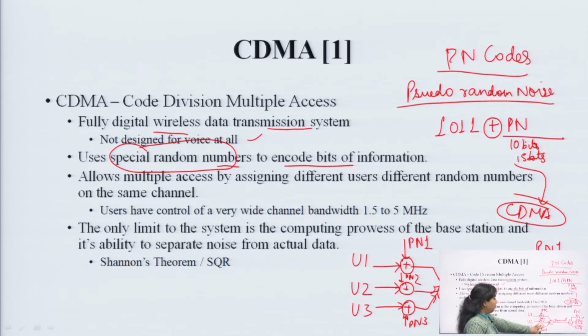So, this is the main point related to CDMA. You have to use the same PN sequence. Let us say I am using PN1 over here, and a different code is used at the second receiver, then whatever signal you have transmitted will not be demodulated correctly, it will not be delivered correctly, it will not be decoded correctly.